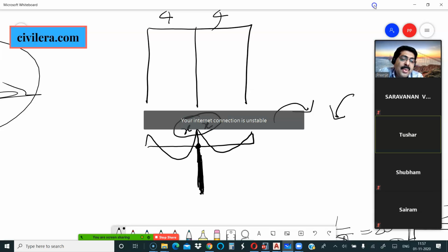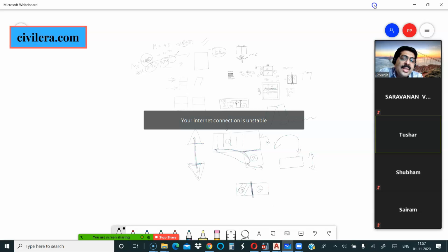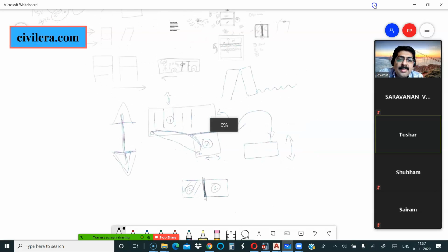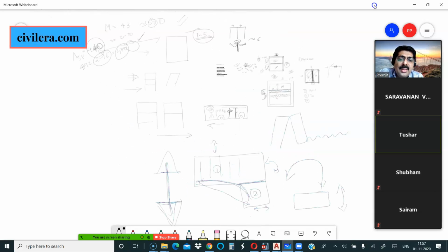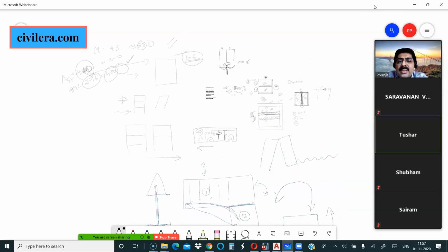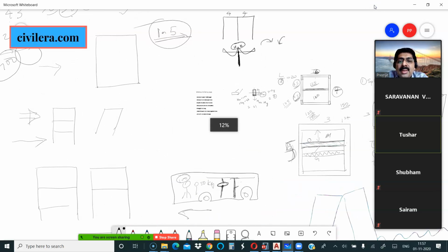So for gravity load point of view, it is a uniaxially bending column. That's the reason I have put it in the other direction. Once I did the earthquake analysis, there might have been many other things changing and deciding that, but gravity load point of view itself, what I have done there is what will be needed.